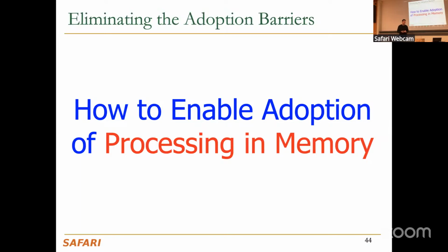How do you know when the operation is finished, especially if it's not a bit-plus operation, but a repeated one where you have to wait n or n squared time? I went quite fast over the background, but what we do is compose what is called a microprogram, which is a recipe that tells the memory controller which sequence of activations needs to be issued to the DRAM chips to do a particular n-bit operation, and over there that n is specified.